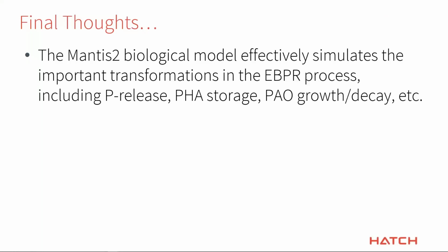I am going to just wind up the webinar here with a few final thoughts about the entire discussion today around modeling biological phosphorus removal. So our Mantis 2 biological model is set up to do exactly that. It effectively simulates the important processes that you get when you're trying to grow biomass, the PAOs, their growth and decay under various different kinds of circumstances, the phosphorus release, the PHA storage, the uptake, the luxury uptake, all of that is already captured into the